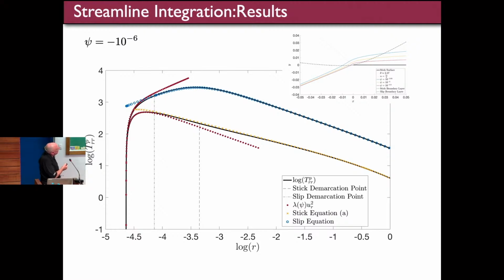That goes through a minimum. And as we're approaching the downstream wall, this stress grows. And once you get close enough to that downstream slip region, that quadratic stress term in PTT and Giesekus takes over and brings the stress back down. So you no longer have unlimited stress growth. What happens with Oldroyd B is that you don't have this blue curve as you approach the slip region. So the stress just keeps on growing.